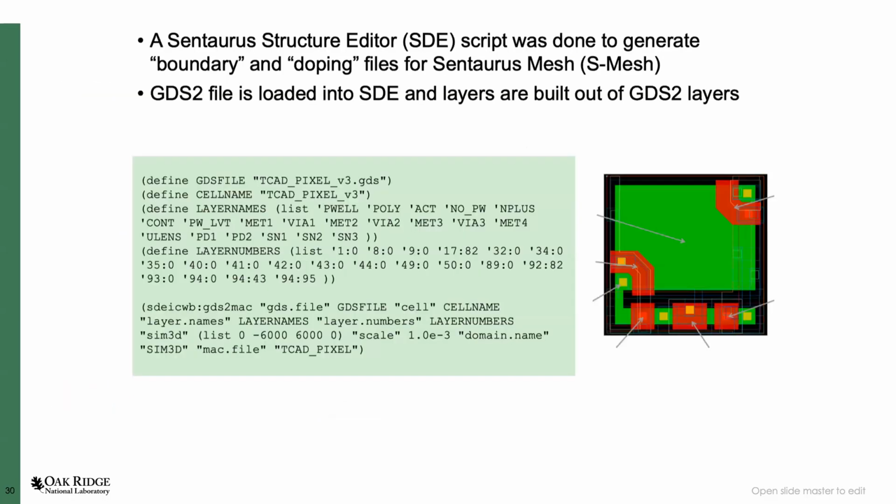And that works in both device simulation and in process simulation. So you can take a GDS file, load it, give names to the different layers, and load that into your process simulation and use these masks during your process, in an abstract way. You say, okay, I apply this mask and I implant everywhere that the mask is not, or I deposit metal everywhere that the mask is. And then you can drive your simulation directly from a design tool.